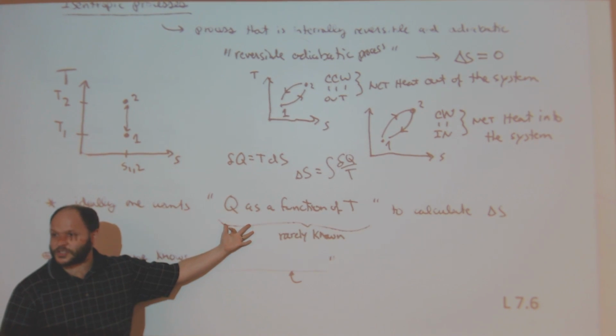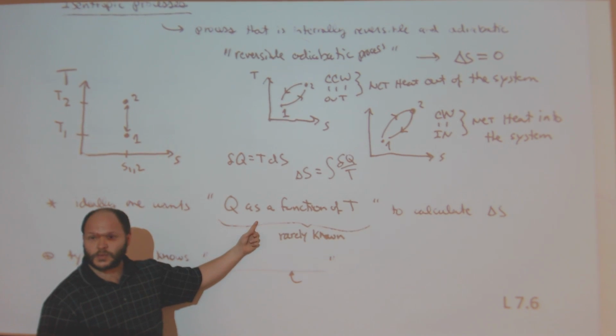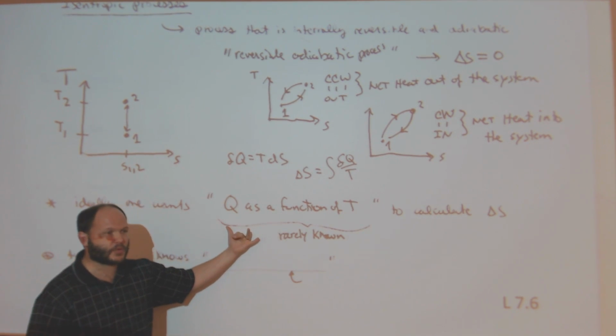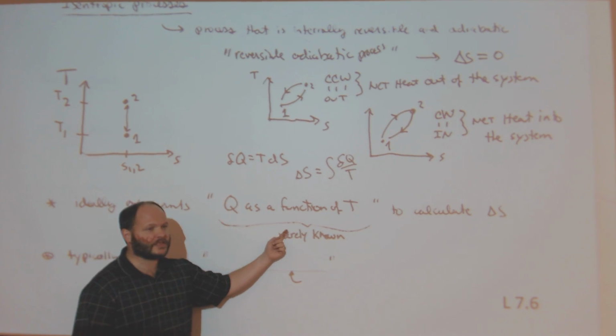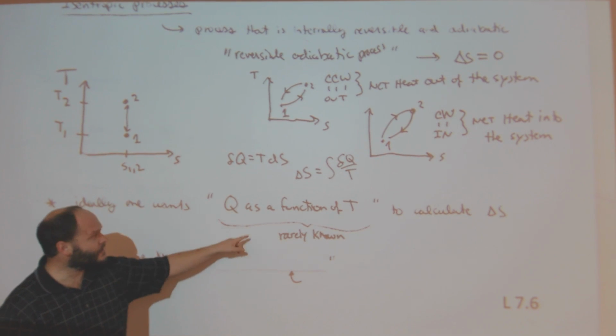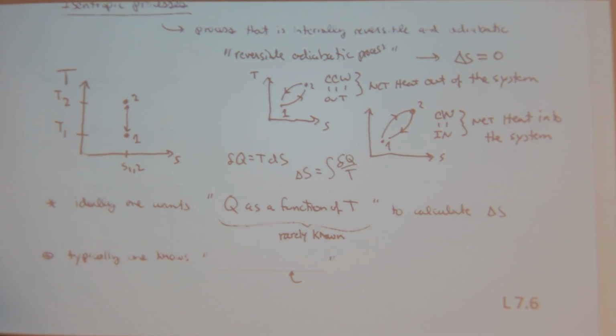But if I take the conduction equation for heat transfer, I have here Q is equal to the thermal conductivity times the temperature gradient. So I have some expression. But the thermal conductivity is a function of temperature, which we really don't know exactly. It's a temperature gradient. And so you can use heat transfer models. They work, but in a lot of cases, it's not precisely known, right?